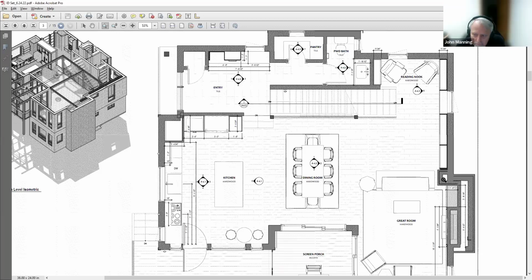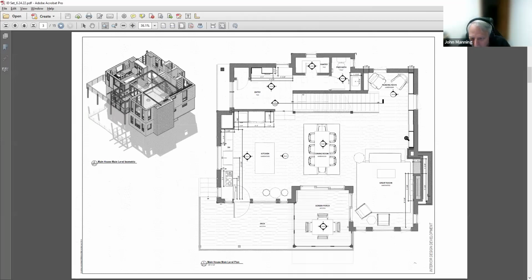within 8 inches of the ceiling, we have to go, I think, left and right to some degree, or north-south in this case, in some sort of soffitted trunk that allows us to go out these floor joists and these floor joists. I'm still picturing some sort of soffit on the first floor.